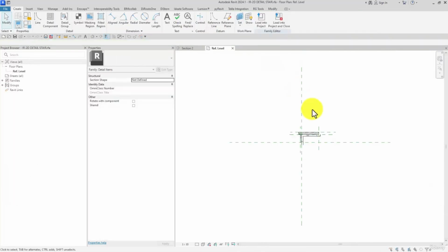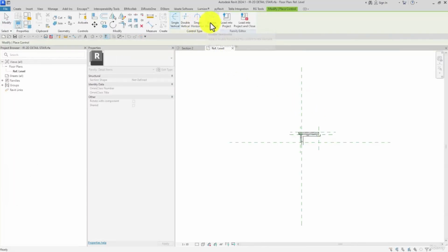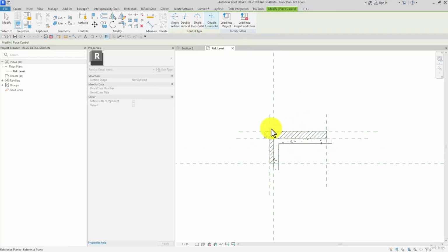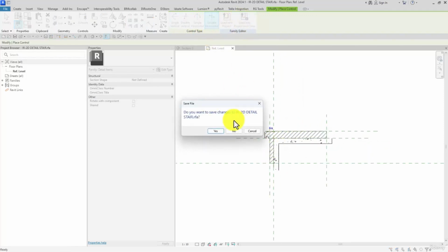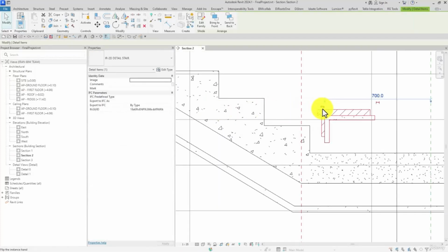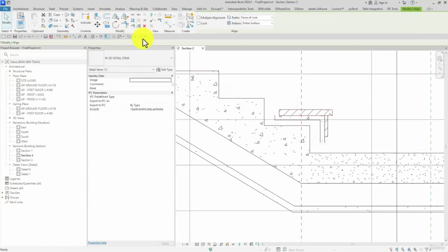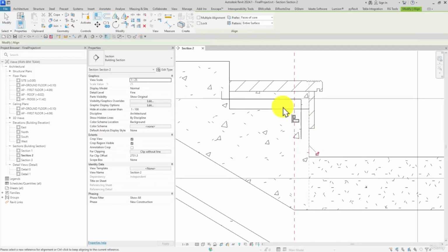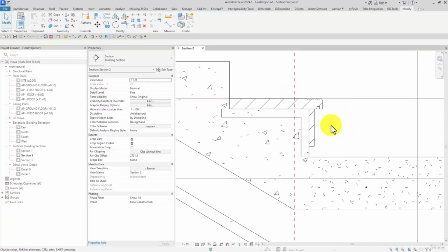Here we have to use the controls. These are at hand. Control and double horizontal. I add the double horizontal, save it, and then I reload it into the project. Watch this, save. As you can see, we add the controls, so we could flip the direction.